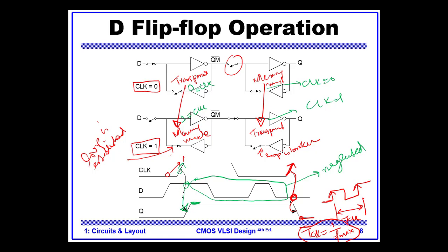It will be 1 divided by 3 gigahertz. The distance between two consecutive edges is your clock period, and it is so fundamental that it determines the overall speed of your circuit. As I told you, we will go into much more detail of how the maximum frequency of a circuit is determined in later lectures.